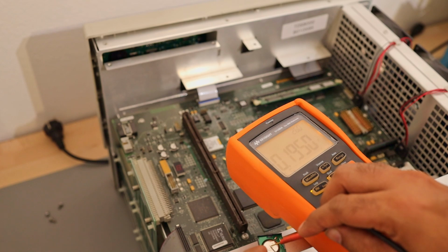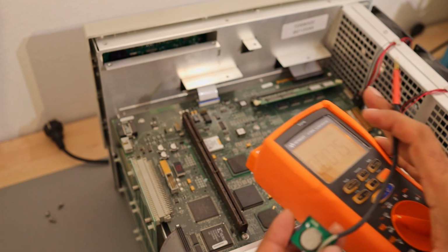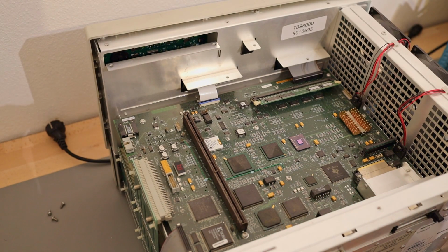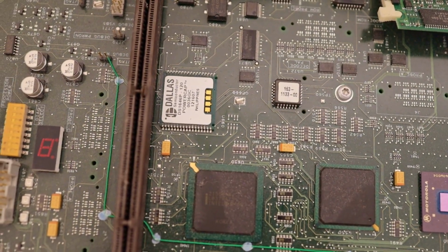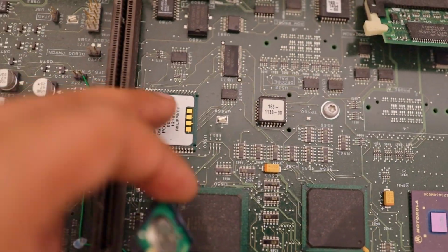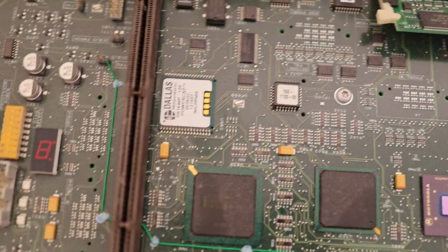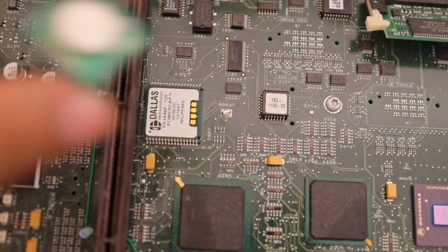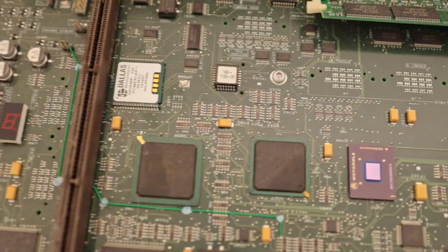This battery is completely dead, absolutely dead. We'll replace this battery. We'll try to install the module one more time, this power cap module, and we'll see how it goes from there. I'll also show you the module. So this is the NVRAM module from Dallas, and 4 contacts paired, which you see on the top. This is how this little power cap module supplies the power to it, and this is where all the VxWorks configurations are stored. We will try to load stuff depending on what this memory says. When this battery goes down, this memory module cannot retain any data, so it forgets everything, and that's how you got this guy not to boot.